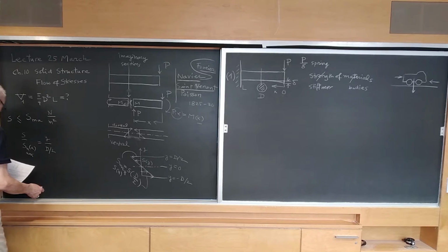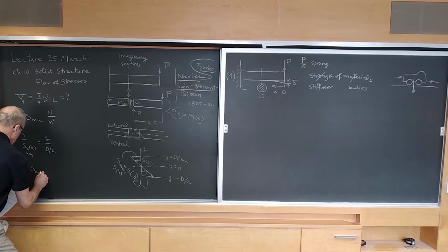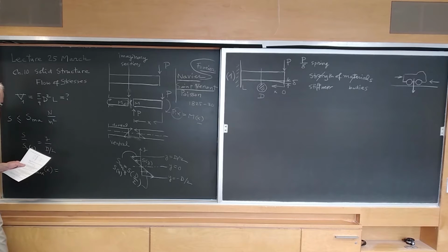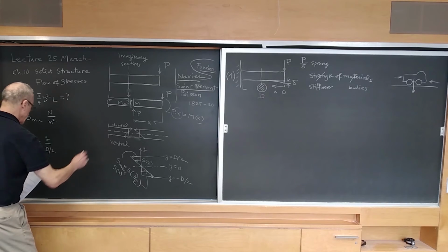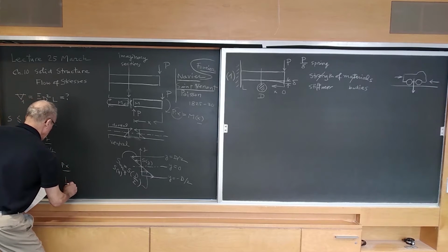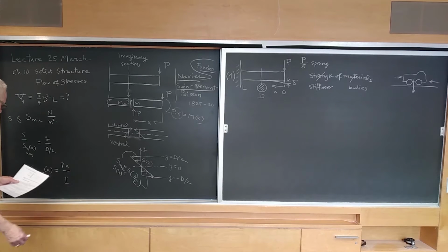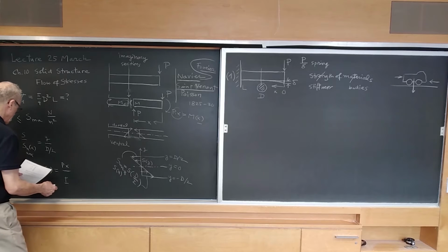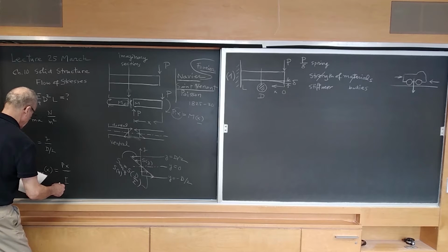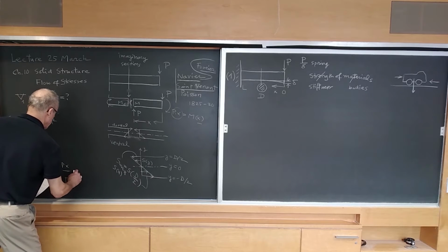The formula for the maximum stress, the one in the upper or lower fiber, is the moment itself divided by the geometric parameter called area moment of inertia of the cross section. So that's I1 in this case, and then y max.